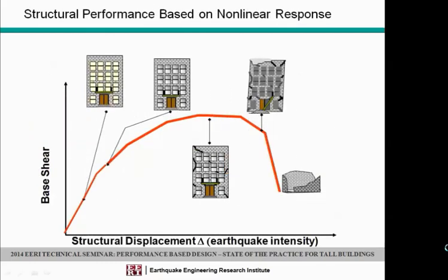If you look at these various performance levels in the form of a pushover curve, and remember that ATC 40 and ATC 33 were performed in the mid-1990s, and while structural engineers knew about nonlinear dynamic analysis in the mid-1990s, it was not something that we regarded as practical for use in practice. In fact, in the mid-1990s, most engineers didn't know anything more than linear analysis, and we thought response spectrum analysis was really high tech.